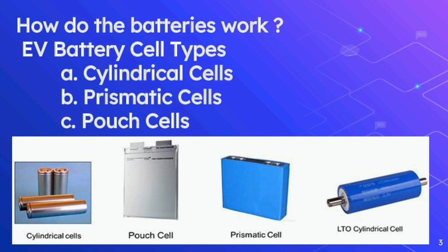Cylindrical cells need to be manufactured in a smaller format than other types of cells to make sure they dissipate heat well, helping prolong the battery life. That's why the most common cylindrical cell formats are 18650 and 21700. Larger formats such as 4680 are available because their new internal design allows more efficient heat transfer to the thermal adhesive used in the structural batteries.